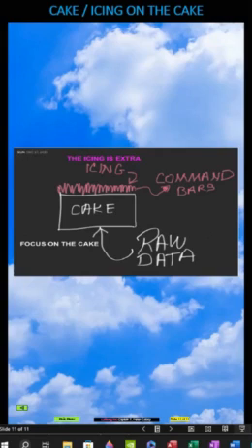So wherever you have an opportunity when executing a departure procedure, or in this case, we'll be talking about an arrival procedure, that is a VOR DME approach to runway 29 in Kabul, you want to think about using the raw data back and forth to compare the computed to the raw data.